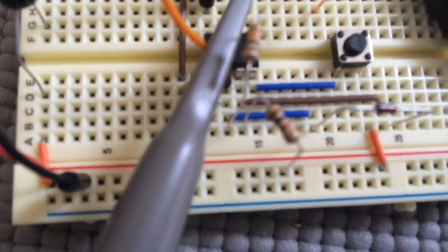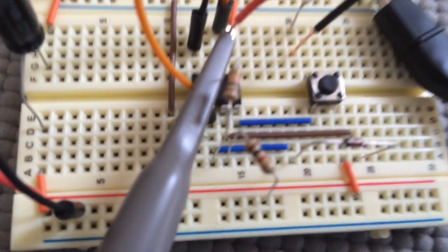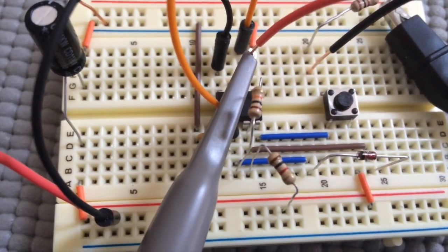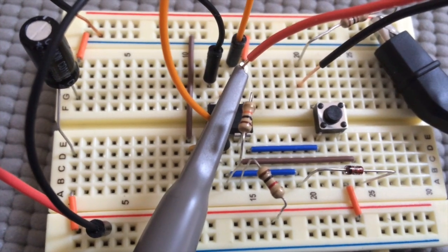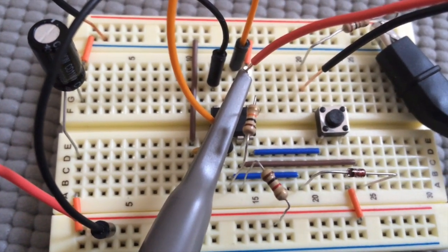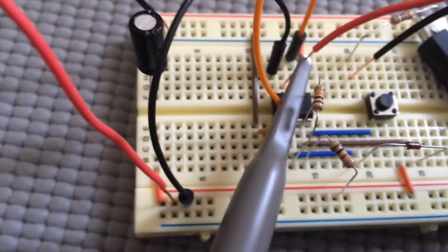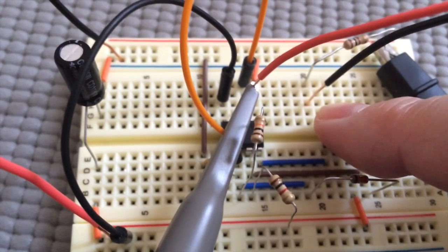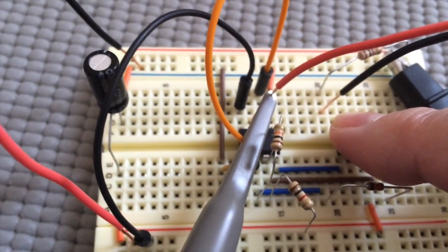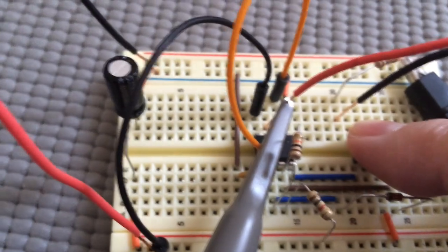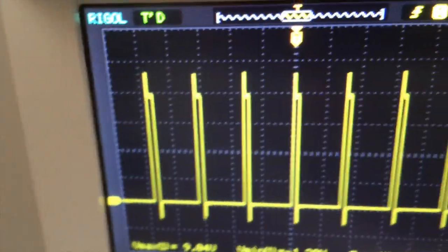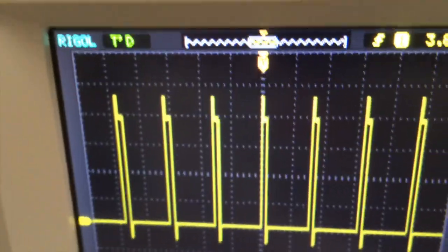Here I have changed the input resistor to have a value of a kilo ohm, while the discharge resistor has a value of 10 kilo ohms. See, we're getting a much higher frequency since the time there is power to the output is controlled by the smaller resistor. Looking at the output, we see that the on and off times are not equal.